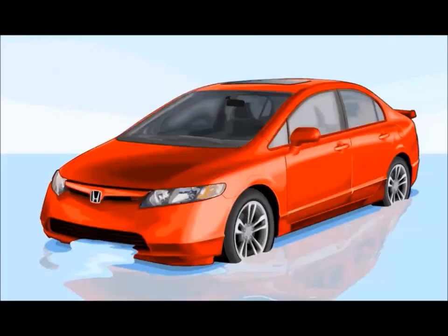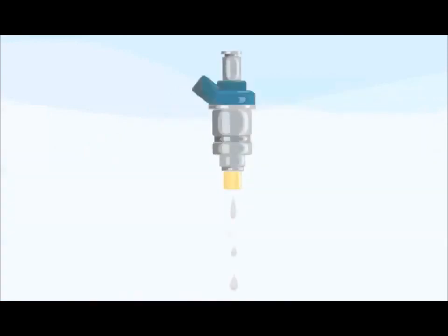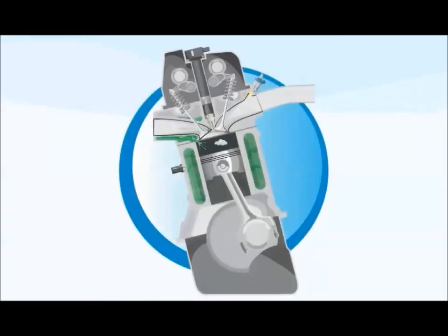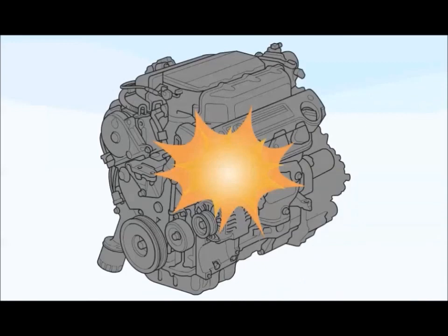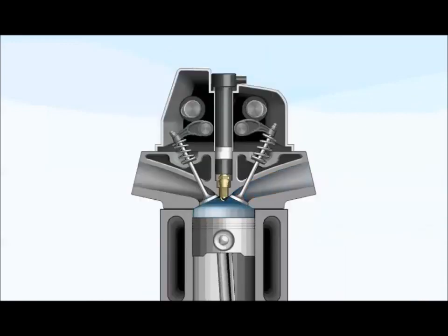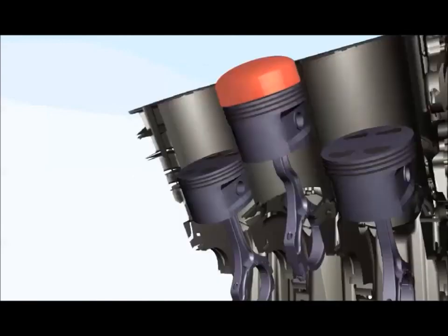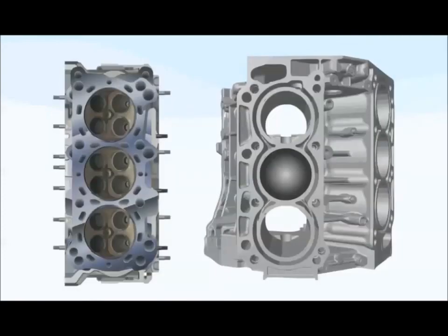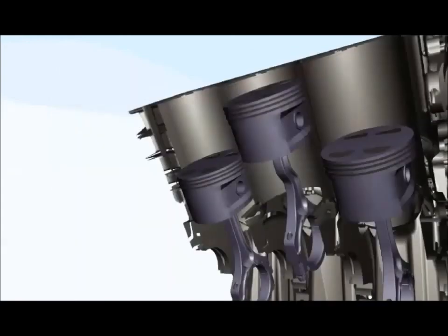Liquids such as rainwater, fuel from leaking injectors, or coolant from leaking gaskets can also damage the engine. When the liquid volume exceeds the combustion chamber volume, the piston stops prior to top dead center, creating a hydrolock. Because liquid presses evenly on all parts of the cylinder, the piston top and combustion chamber do not show any marks or nicks. Instead, the connecting rod bends to make room for the liquid.